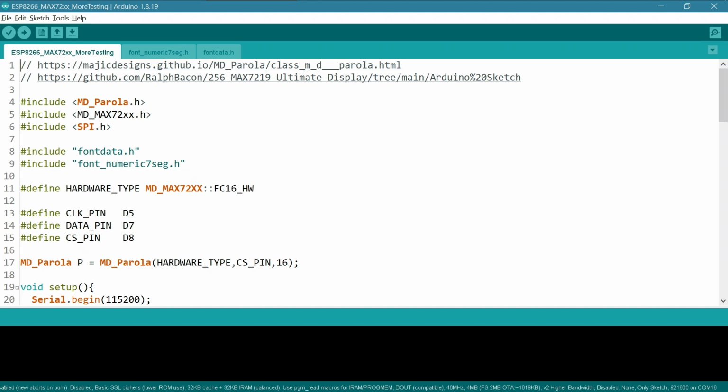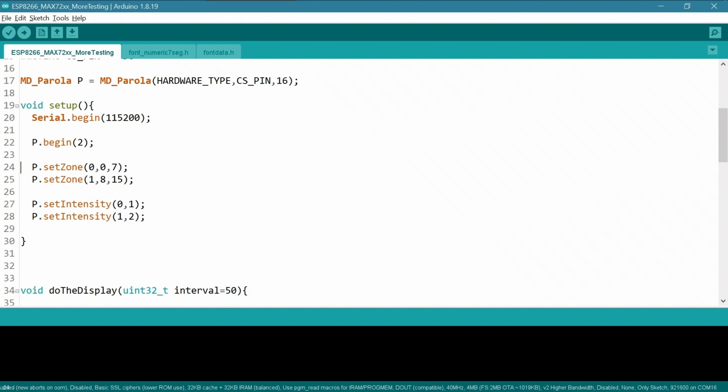So this video helped me more than all the documentation because it showed me some things I never would have come across. For the little ESP8266, there are some defined pins because we use SPI in here. So you can't change these. If you want to build this, these are your pins. No way around this.